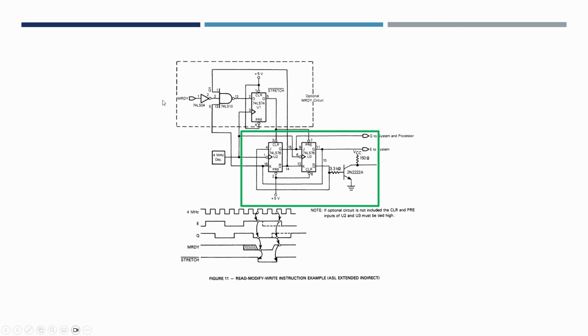this little bit here. The MRDY at the moment, if we keep it as it is where it goes low, which I think is the convention on all 6809 designs, then we should have a situation where, when this goes low, we would get one or more of the oscillator cycles added onto the E signal, and what that should do is also extend the Q signal as well. So both the E and the Q should extend when the MRDY goes low, where we get this stretch period effectively here. So that's what we're going to do on the clock area of the board in a minute.